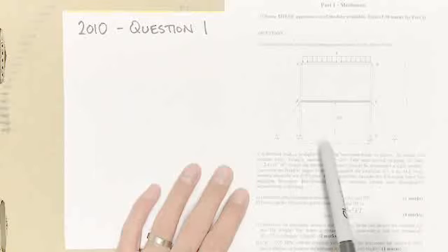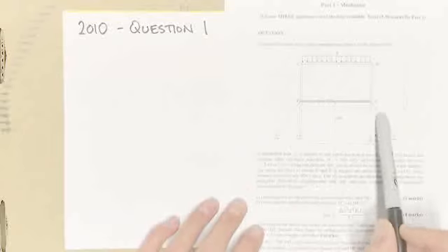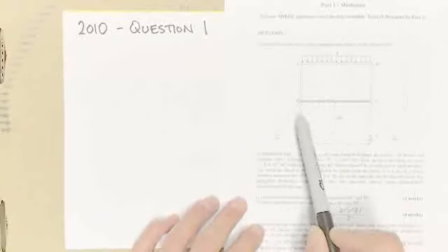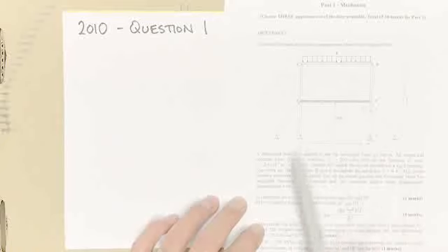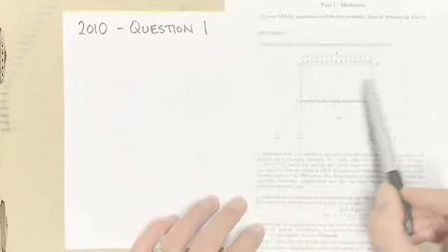Well, I could go into a more detailed explanation, but basically they're going to stop B and E from moving horizontally. Okay? The purpose of this rigid beam and these wires is to stop points B and E moving horizontally, in effect constraining these columns in the center.